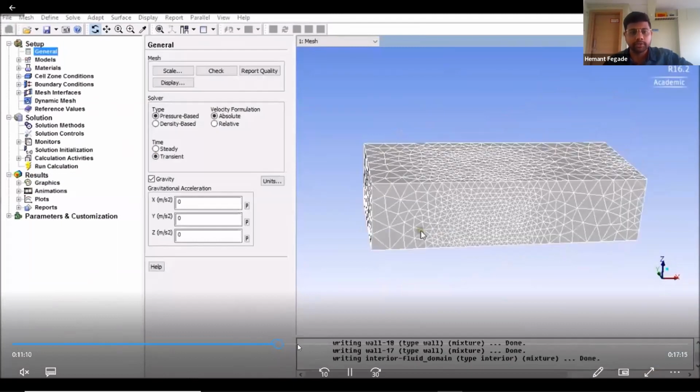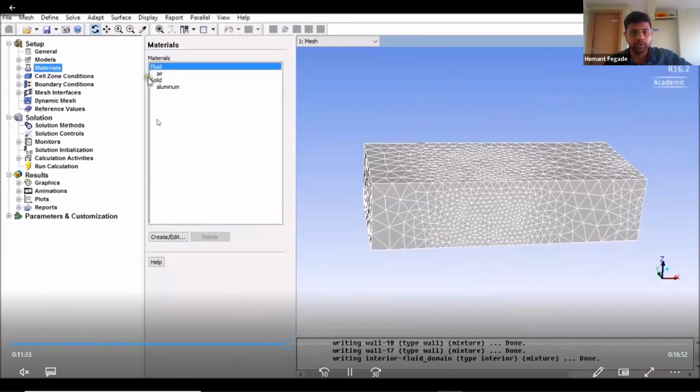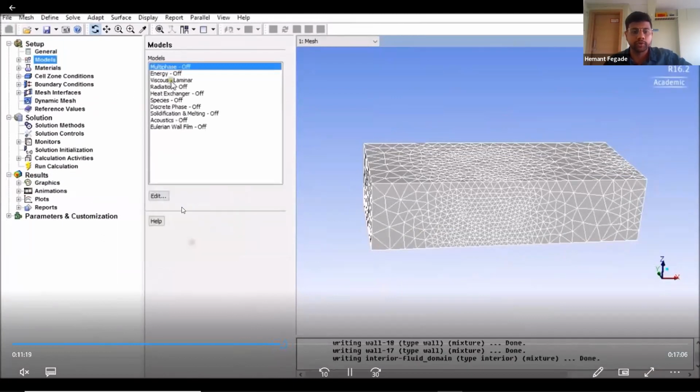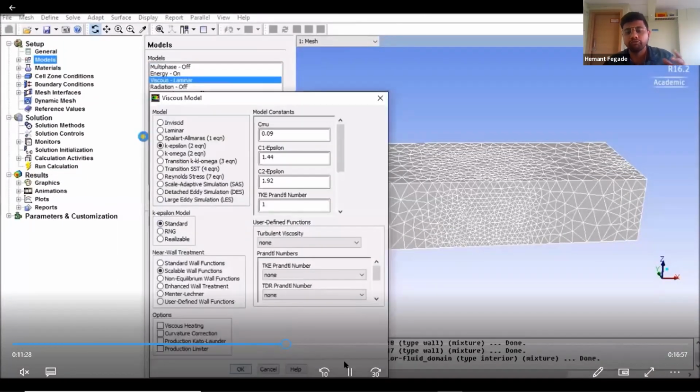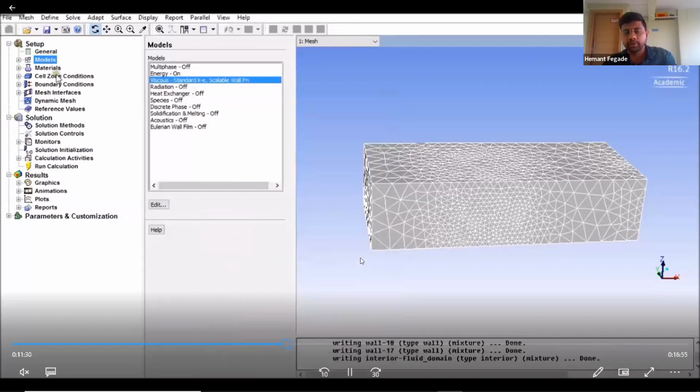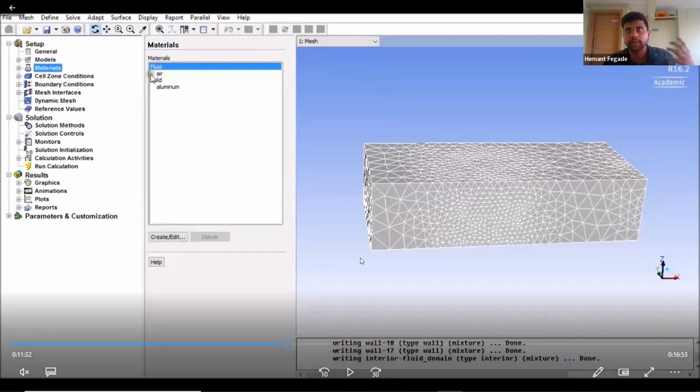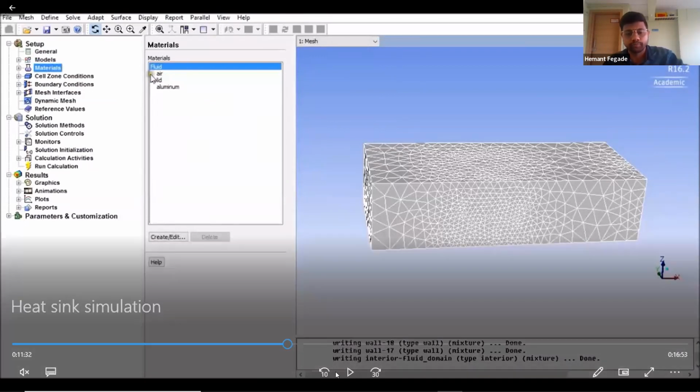Essentially you'll be defining first the models that you're going to use. First you'll turn on the energy equation to establish the temperature factor. Then you will select the turbulence model, k-epsilon with the scalable wall function. Scalable, because we can scale this model up to a larger domain to get a good grasp on the properties, because it's very miniature if you consider its original size. So we need to scale it up in order to magnify the regions of interest and to understand the flows, right?